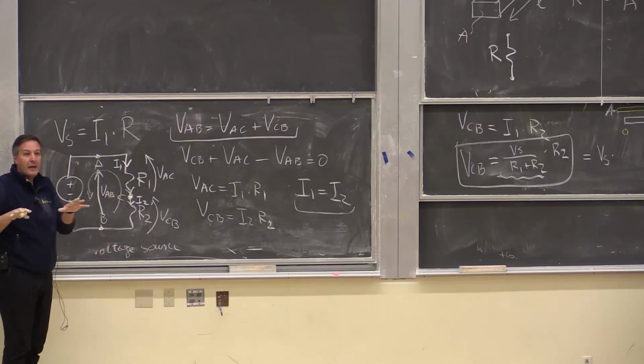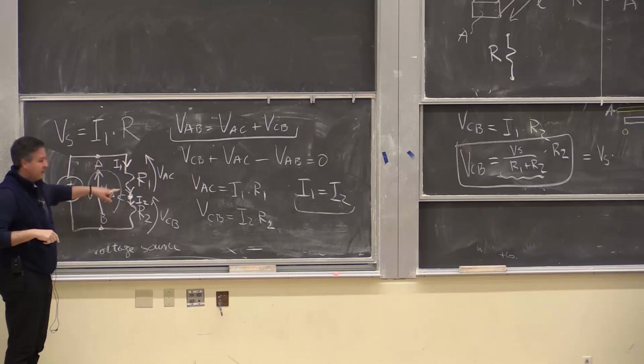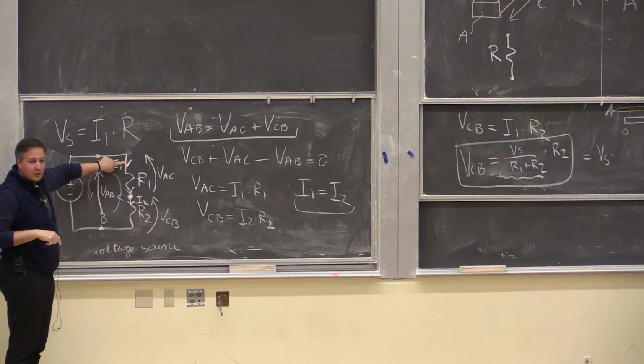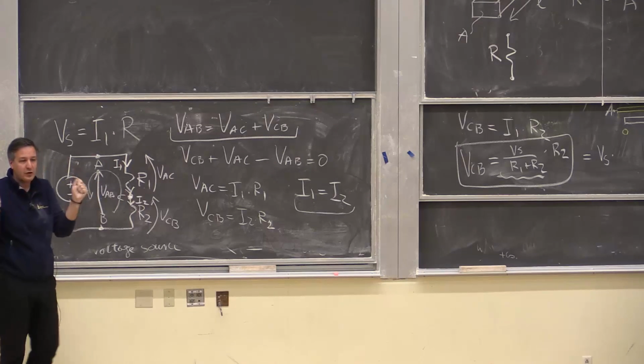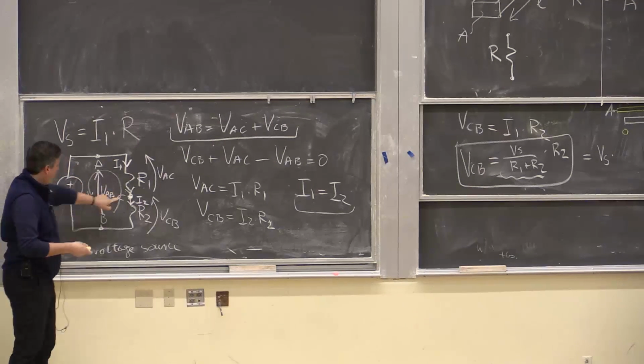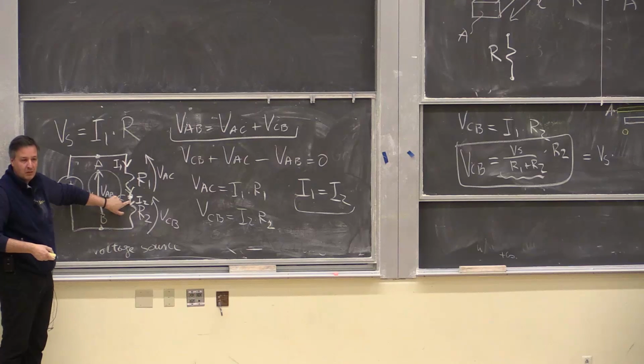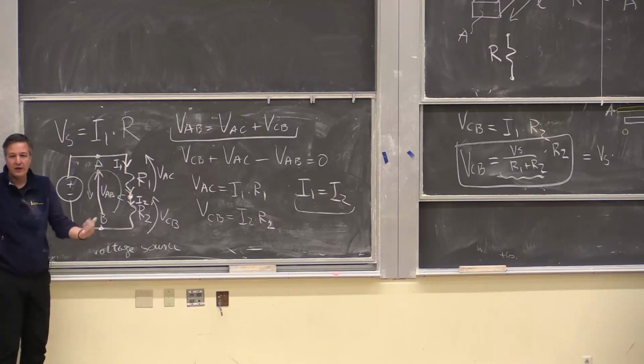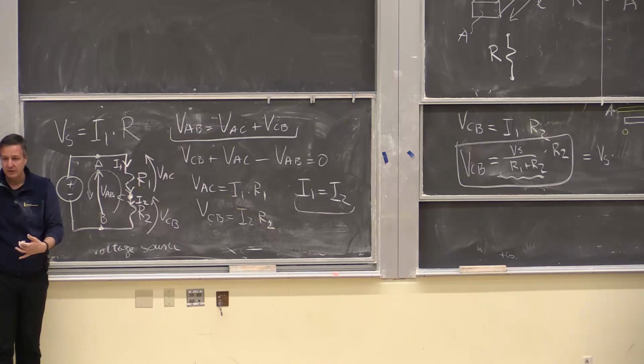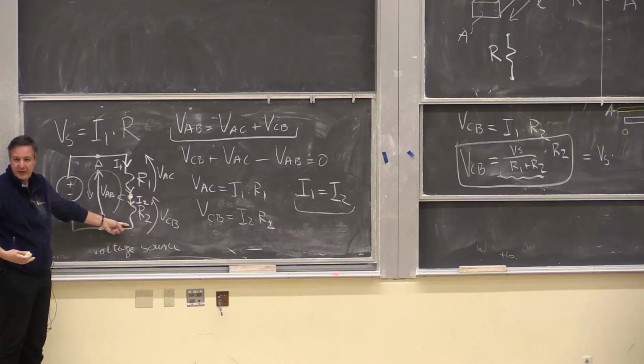Okay, so just for maybe some people who were still confused. The current that flows into the resistor is the same as the current coming out of the resistor. It's still one branch of the graph, right? All the way until we hit node C. Then in node C, we say, okay, is there anything else coming into this node, right? Because multiple edges could be coming in. In fact, edge 2 is coming out, right?